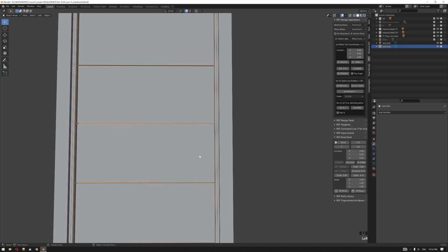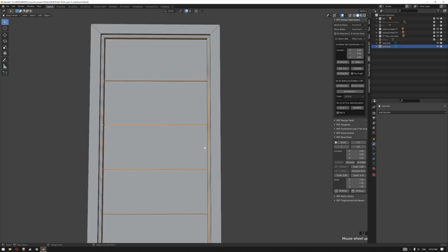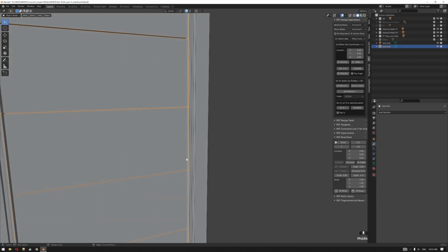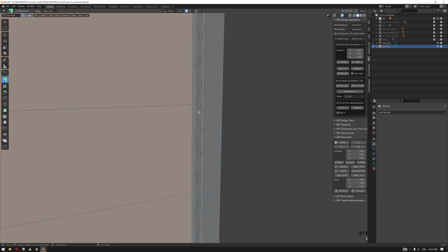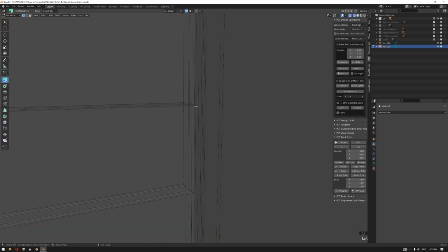Last thing is the door handle. So we're gonna place the door handle at this part. So we need again to place our first shape by identifying the center part of this part between these two vertices. So I'm gonna go to wireframe, select these two vertices, and again using the BDT add-on by pressing 50%,